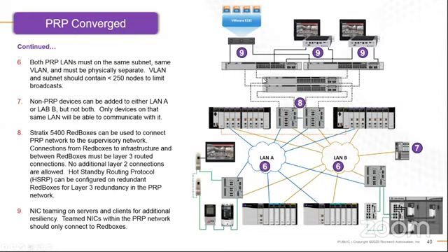You'd still have your resilient network up top for a redundant star topology. Again, we can handle this and mix and match designations. So we can do redundant star or ring topologies, but you would have your dedicated communication, one for upstream, one for downstream. You still have your 7 cards that you're able to do. And you still have the ability of being able to do NIC teaming as we start seeing up top.